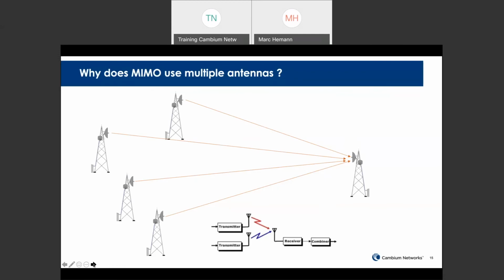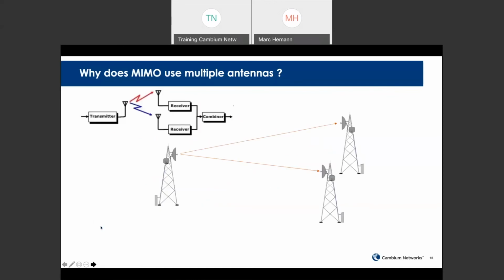Diversity, both transmit and receive, is a method of using multiple antennas to survive the negative effects of multipath. As the distance between a transmitter and receiver increases, the received signal strength decreases and gets closer to the noise floor. So your signal-to-noise ratio drops, and bad things like a dropped signal or decreased data rates will start to occur. With a diversity system, as I mentioned earlier, listening with 2 antennas increases the odds of hearing at least one signal without corrupted data, and your odds get better with 3 or 4 antennas. When receive diversity is used, the signals will be combined, allowing for a better estimate of the original signal. This effectively produces a stronger received signal with an increased signal-to-noise ratio.